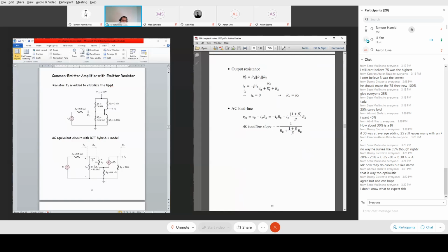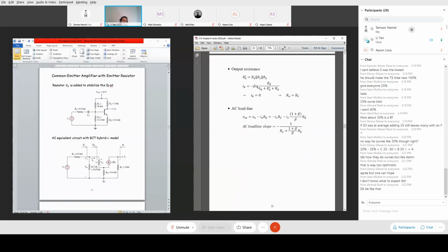Left side is I sub B. The right-hand side is also related to I sub B. If I move I sub B from the right side to the left side, I can factor out I sub B, with the remaining quantity being 1 plus this quantity, which is non-zero. The product of I sub B and the non-zero term must be 0. I must conclude the solution is that IB itself must be 0. So that's why I can determine IB itself to be 0. Even for this circuitry, it's not obvious, but I can still work out step by step that current IB is 0.